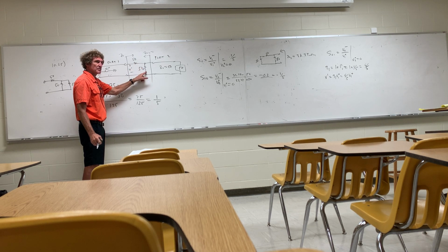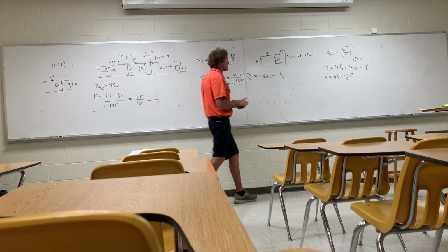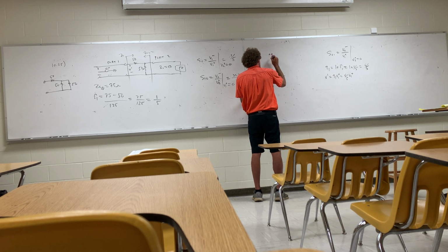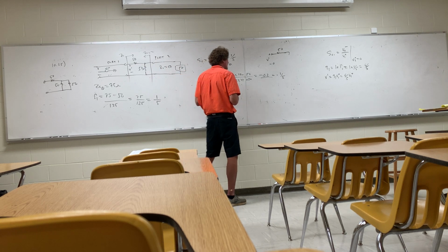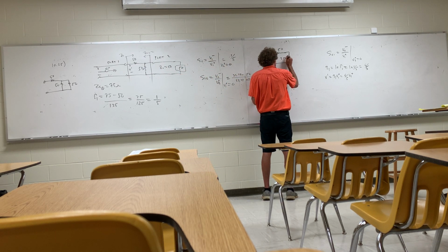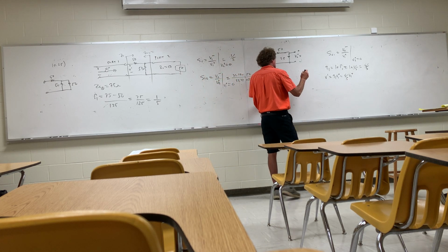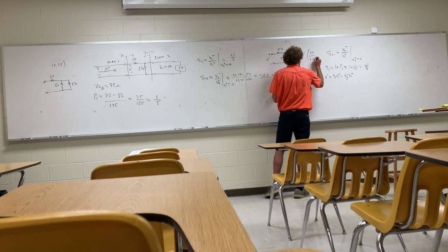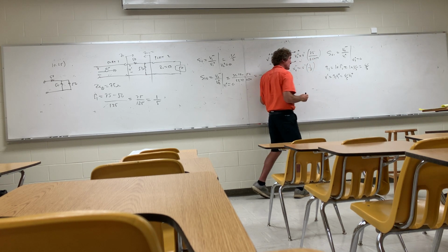Then I have this voltage division that happens. Take a moment. I've got 50 ohms, but it's in series with a parallel combination of 50 and 50. So, we do it up here. When I look at that, this is where my V prime is. And now I've got 50, and then the parallel combination of 50 and the transmission line 50 ohms is going to be 25. And what I really want is this voltage right here. That would be V2 minus. Y'all follow me? So what's that going to be? V2 minus is going to be V prime, the voltage across this series combination, times simply 25 over 25 plus 50, or V2 minus is equal to V prime times 1/3. Do you agree with that?